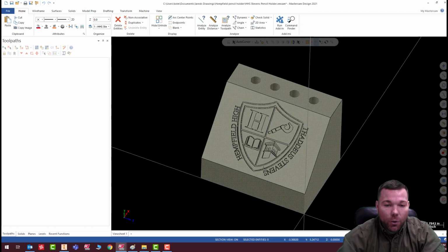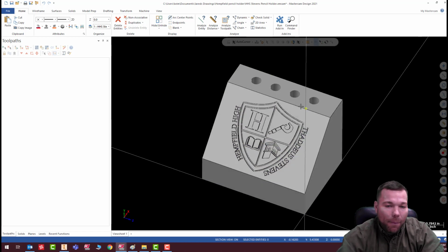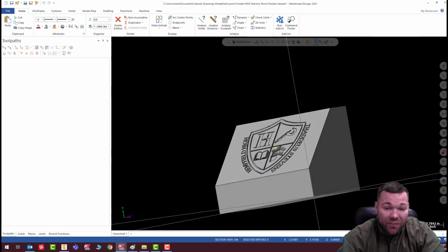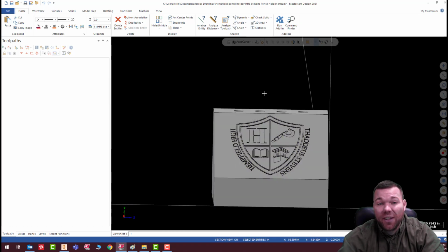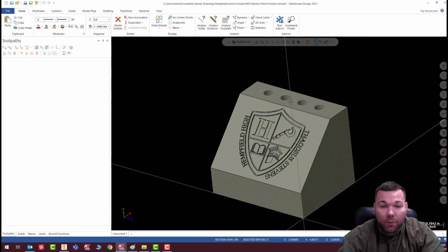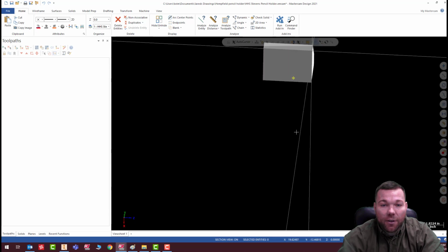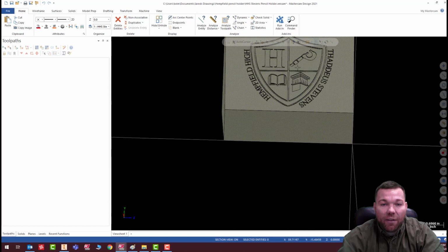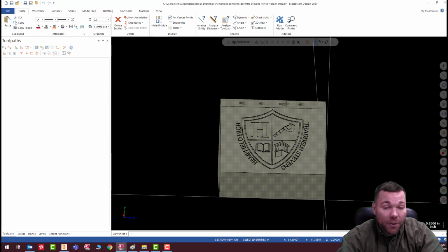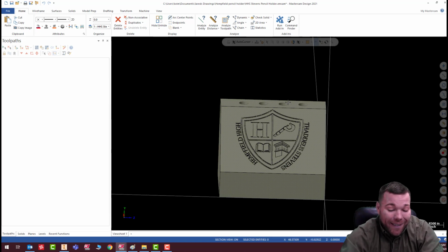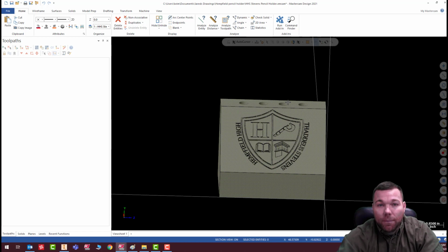Since we've decided that we're going to mill every face of this part so the whole thing looks good, doesn't have the dull stock finish, that means that we have at least 6, 7 setups here, right? Because we have 7 faces. We have 1, 2, 3, 4, 5, 6, and then our engraving face would be 7. So we have 7 setups here, potentially. Well, when I get to that many setups, chances are I'm not going to use a 3-axis mill. Unless that's all I have, of course. Then I would use a 3-axis mill.